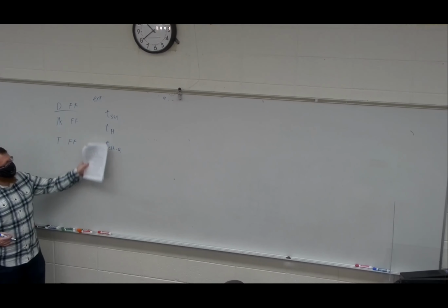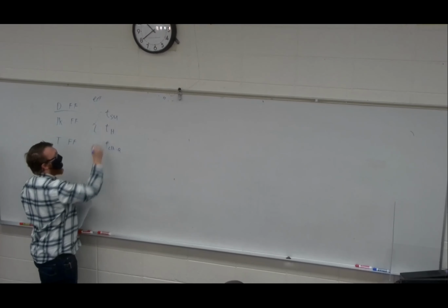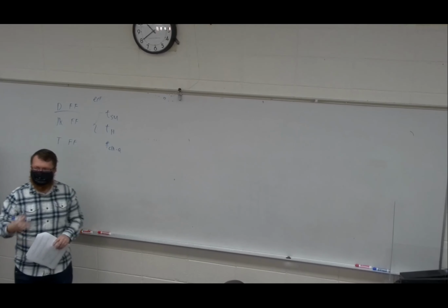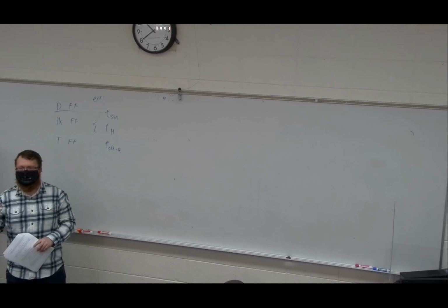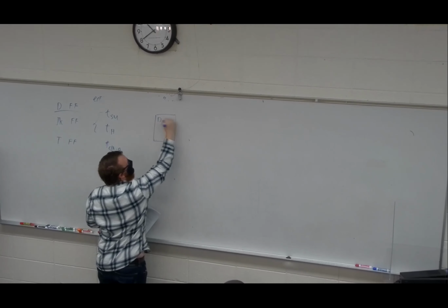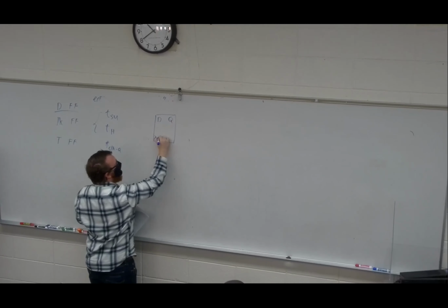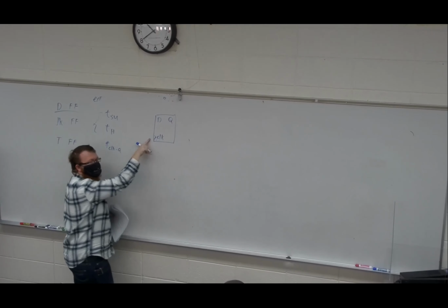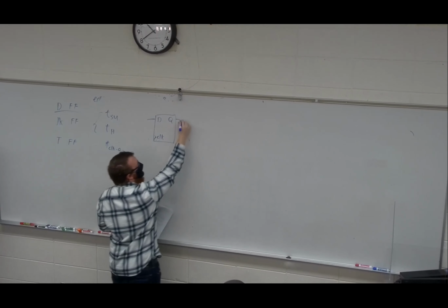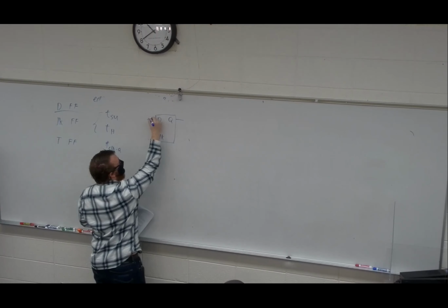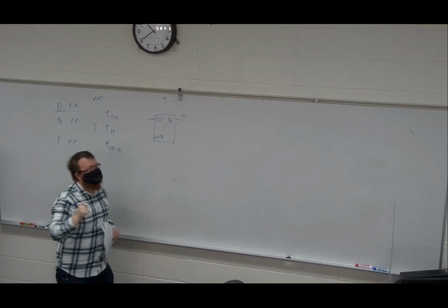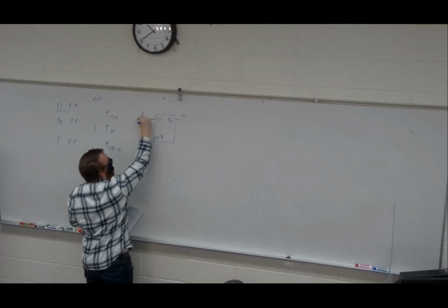So these are timing requirements that you need to meet in your system. The clock to Q is a little bit different, but it's still a timing requirement. It just says, if I have this D flip-flop, and I get a rising edge on that clock, and say Q at time 0 is 0, and data at time 0 is 1.